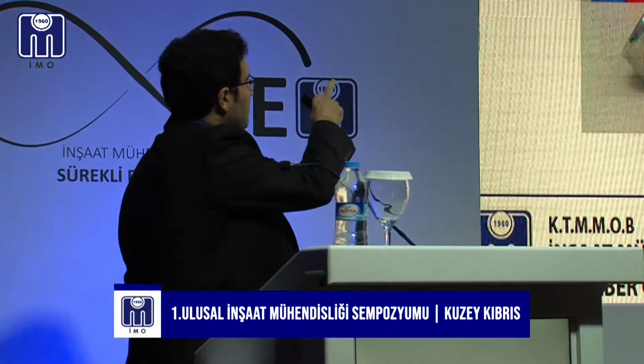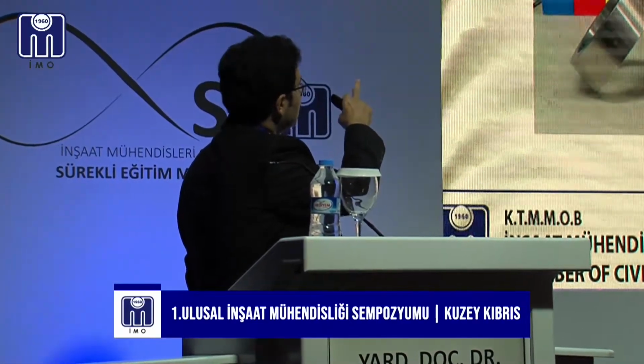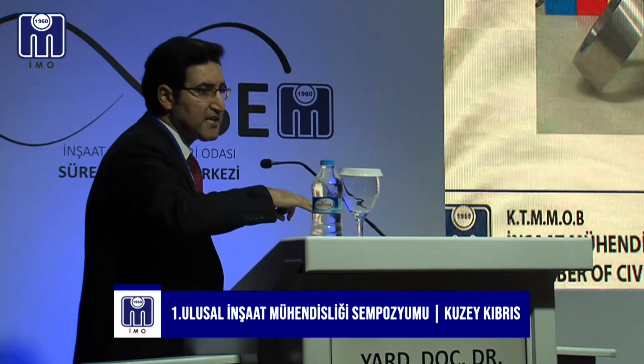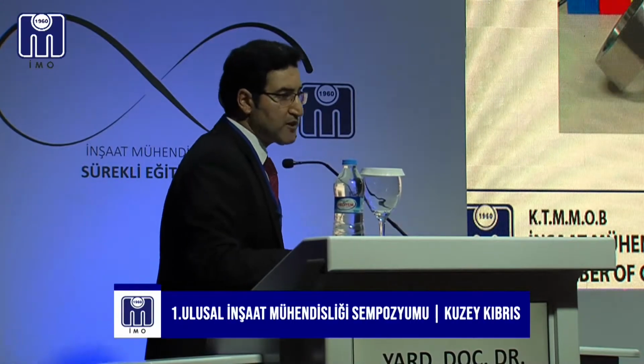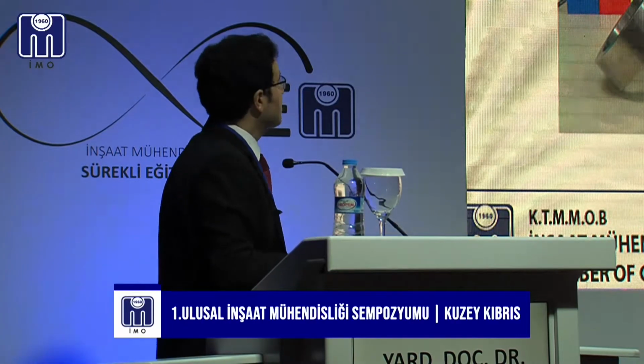This is for finding the value of e_max. We have to put the soil in 10 layers, and for each layer we apply 100 impacts on the 4 sides of the mold.